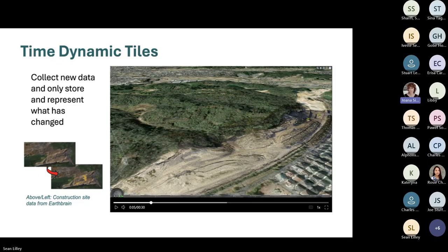Yes, exactly. If I want to share my point of view as a construction engineer, in our industry it is really important for us to track the time and cost of the project. The cost would be another attribute that we can add to these 3D models, as 5D modeling. We have a concept called ND modeling, which is added with different kinds of data. For example, if you add time it would be 4D modeling, if you add cost it would be 5D modeling.